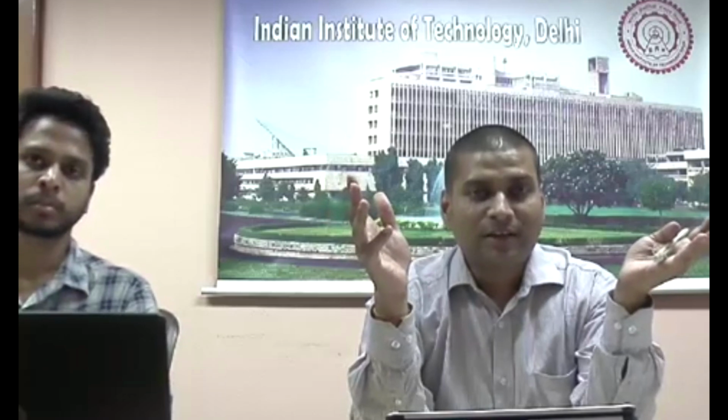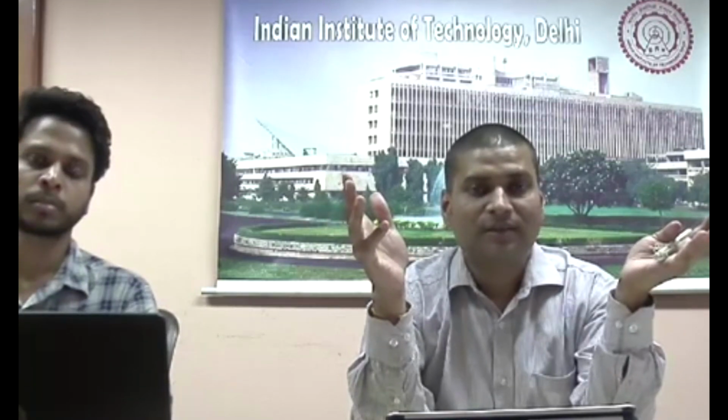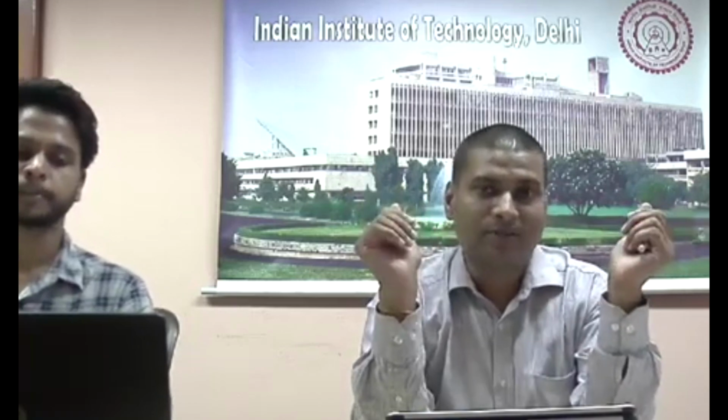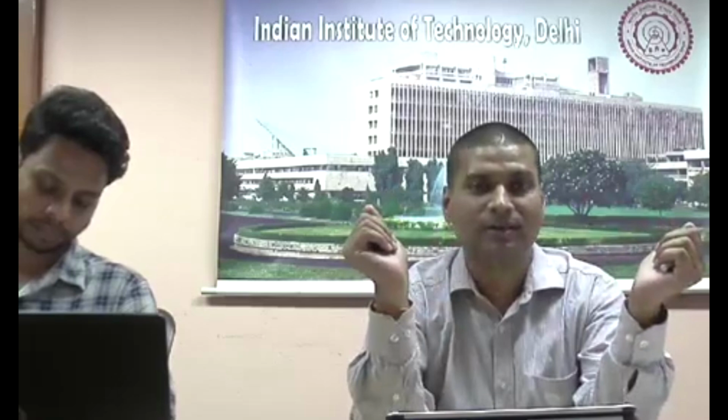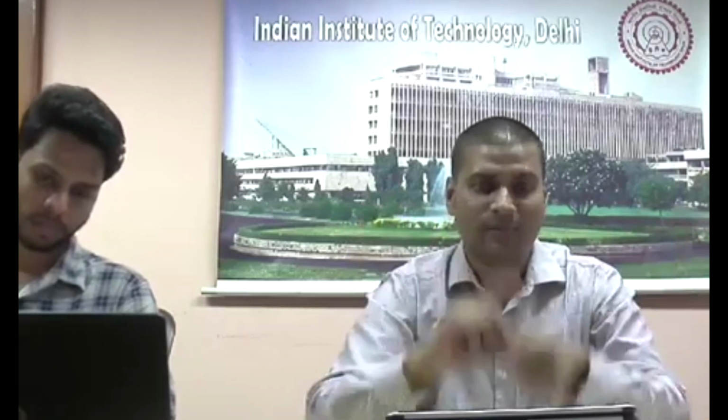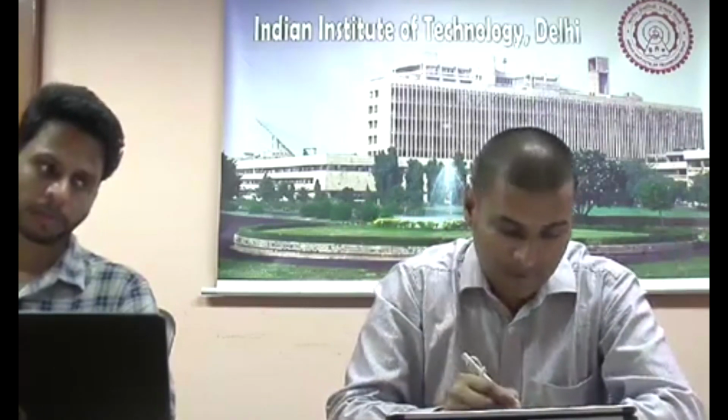So with the presence of body couple, when you work out the angular momentum balance, you will see that the stress tensor is no more symmetric. For such theories, which are advanced theories of course, the Cauchy stress tensor does not turn out to be symmetric. But otherwise, for the domain of this course, which is a first course in solid mechanics, we always think that the stress matrix, or stress tensor, is symmetric. Alright, let's see what more questions we have.